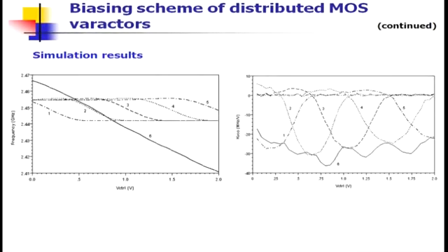So, whatever my voltage, it is not going below my threshold voltage. So, maximum delta V available is say 0.2 volt, and I have 100 megahertz. So, 0.2 volt and 100 megahertz means 200 KVCO. Here it is roughly like 150 megahertz per volt. Clear? Now, I am giving the task to 5 or 6 such varactors, and they are adding.